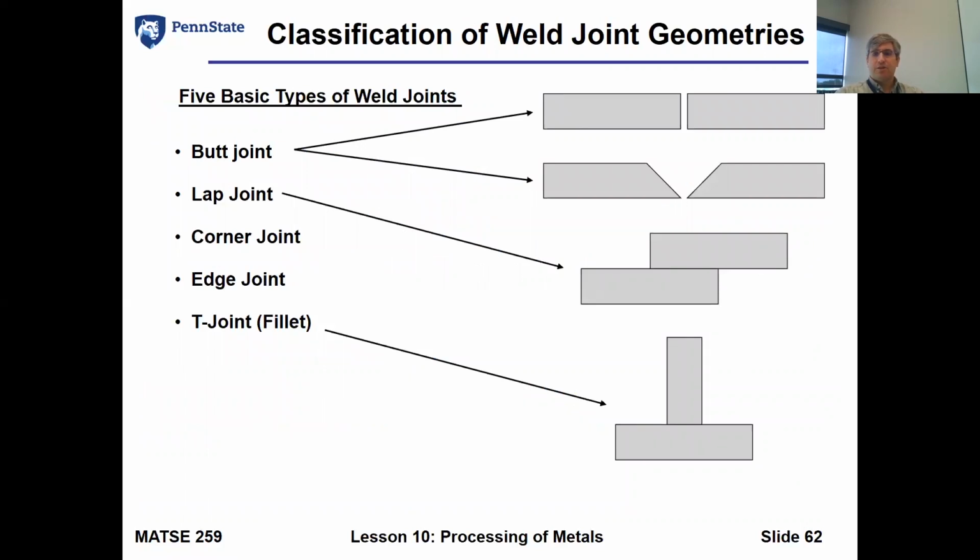There's some different joint geometries. I just want to bring these up because people will tend to use these. And if you go to work in a fabrication house, you're just going to be expected to know what they're talking about. So butt joints can either be straight butt joints across the thickness of the material, or you can add a V. They're still butted together with each other.